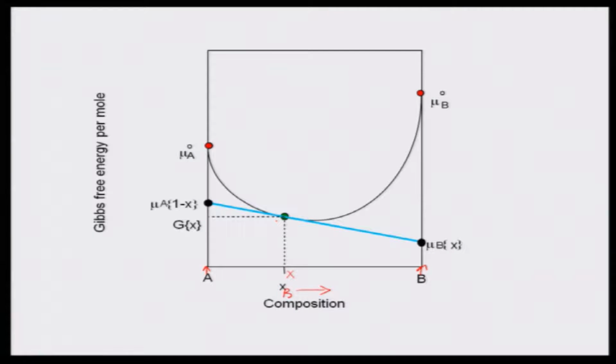In that case, these two ends will give you the chemical potential of A and chemical potential of B. Now if we consider this is for phase alpha, this is free energy of alpha, and this is how the chemical potential can be measured easily, graphically. Why is it the tangent to the curve rule? That also needs to be discussed, we will discuss later why the tangent to the curve tells you the chemical potential of the two components at the ends.